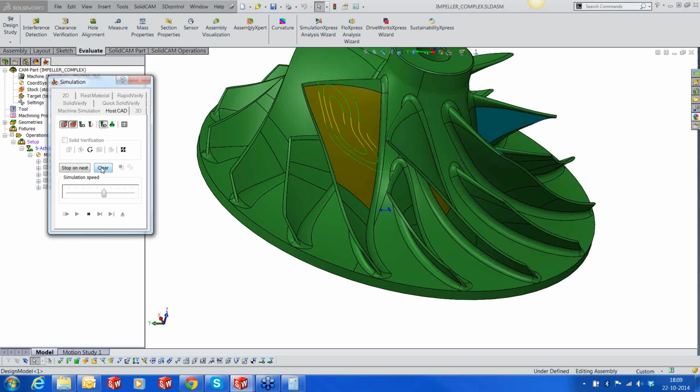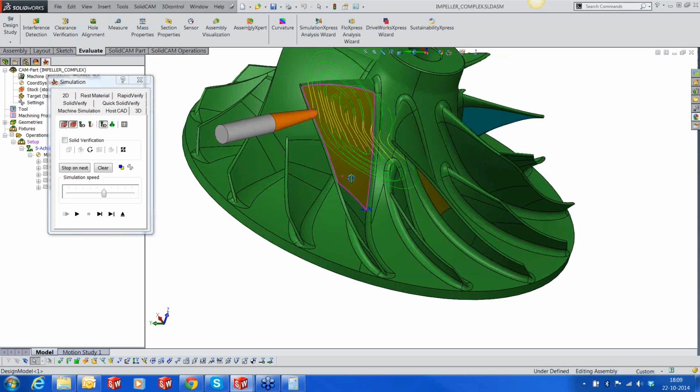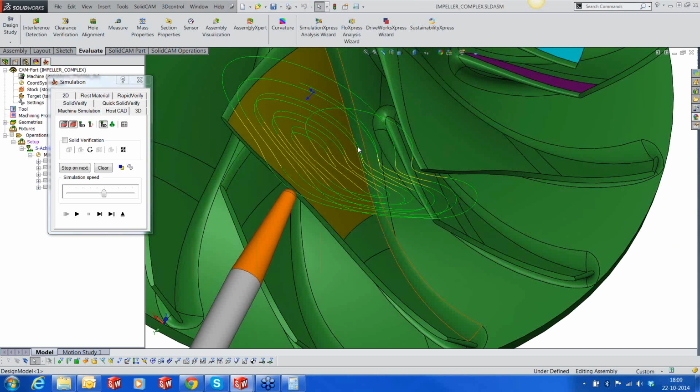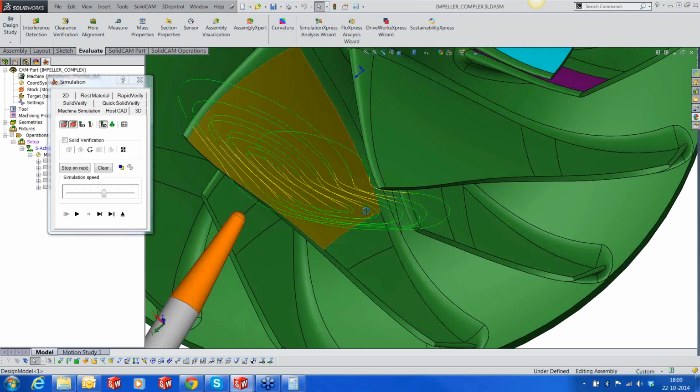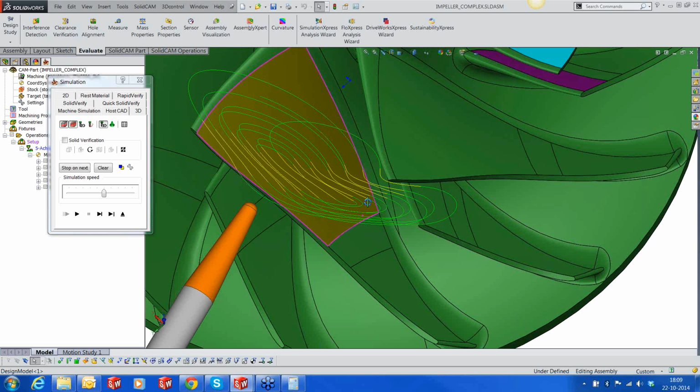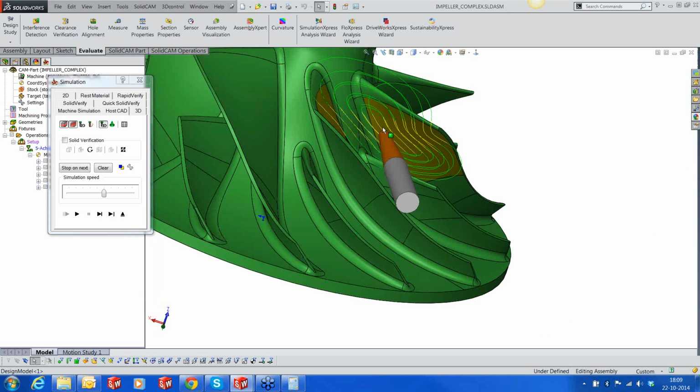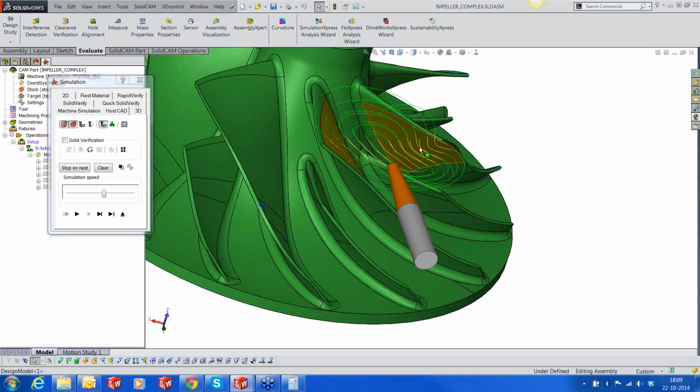You can see that. We're going from the center and we're going out. All these connections, by the way, are automatically done by SolidCAM. The external connections which you're seeing in green are basically connected automatically by SolidCAM. They save a lot of air movements, and when it's moving from this point to this point, it's already taking the depth of cut. So it's done very nicely, and you can see these movements very nicely on the machine. There are no jumps on the machine as such.